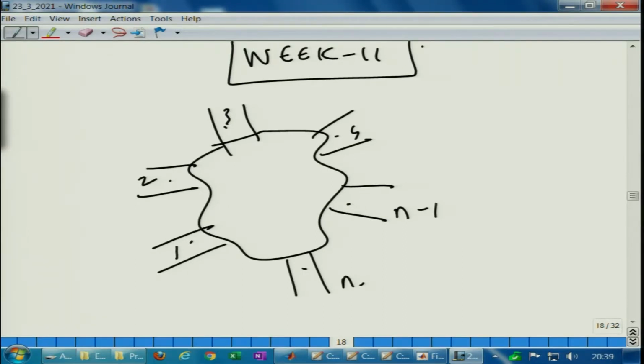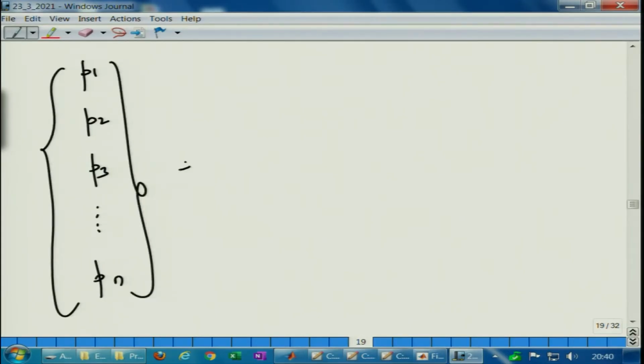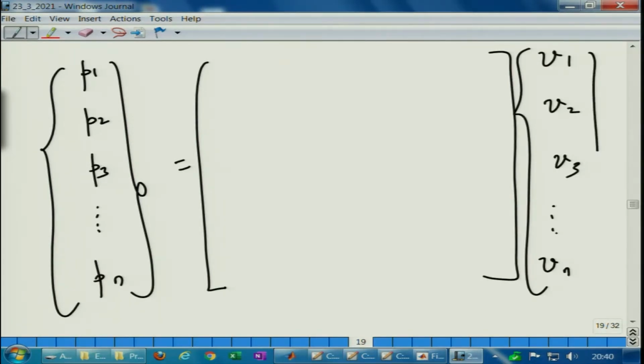If we recall our discussions from the later parts of week 9, or the initial parts of week 10, you will see that an impedance matrix is the best way to characterize such a system. I am dropping the tildes, excuse me for that. So, here you have this kind of a thing, such a matrix. So, what is that matrix called? Where we relate pressure to the acoustic mass velocities at the different ports. Such a matrix is called an impedance matrix.